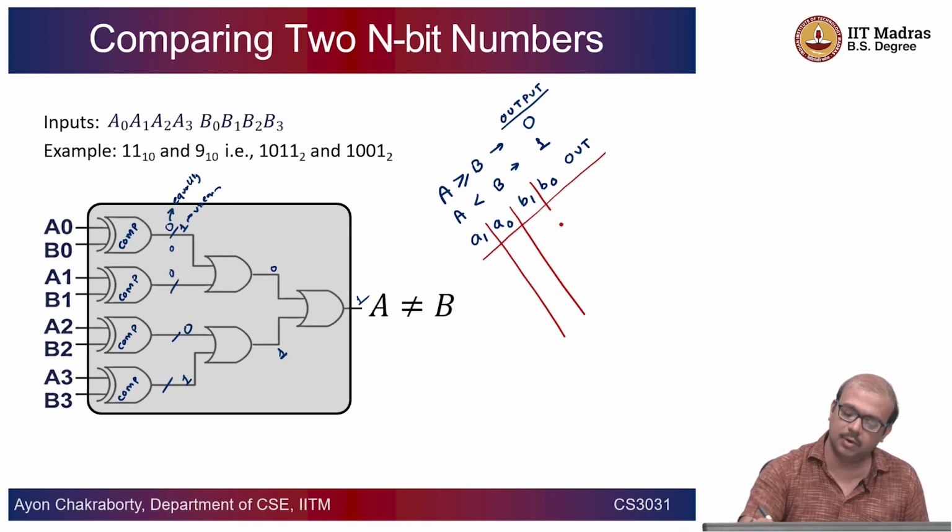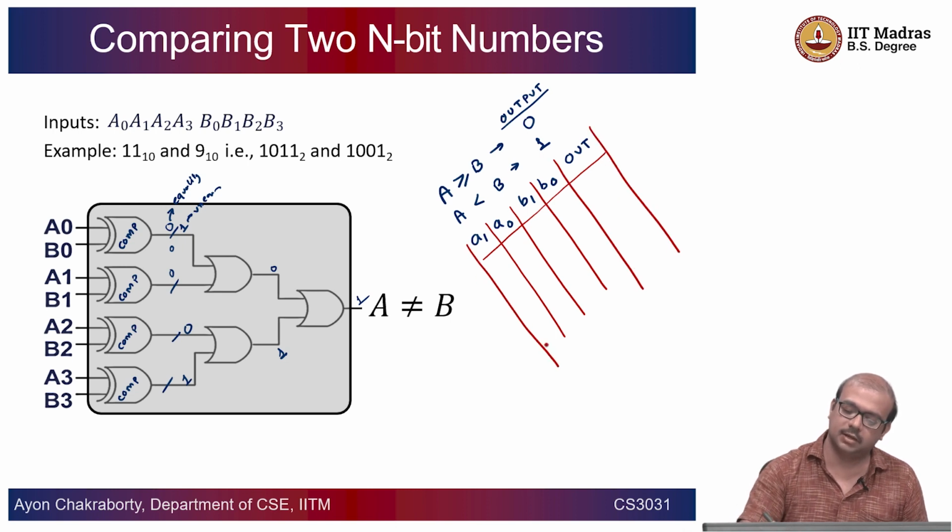Okay, I will do a little bit and then you can carry forward the rest. So, whenever you get this kind of problem, you have to write up the truth table. There are 4 inputs together, right. There are 2 numbers, each number is a 2-bit long thing. So, you are going to have 16 entries first of all, from 0 0 0 0 to 1 1 1 1.